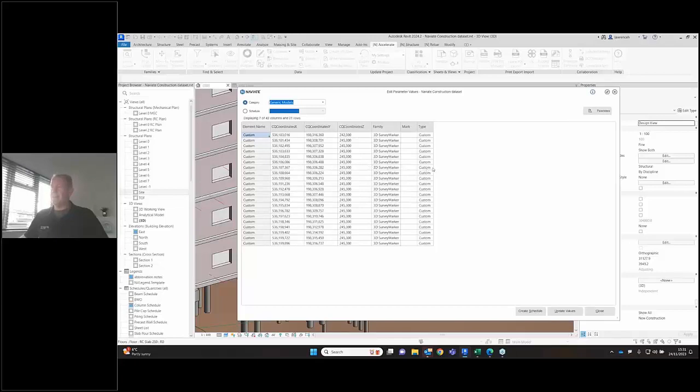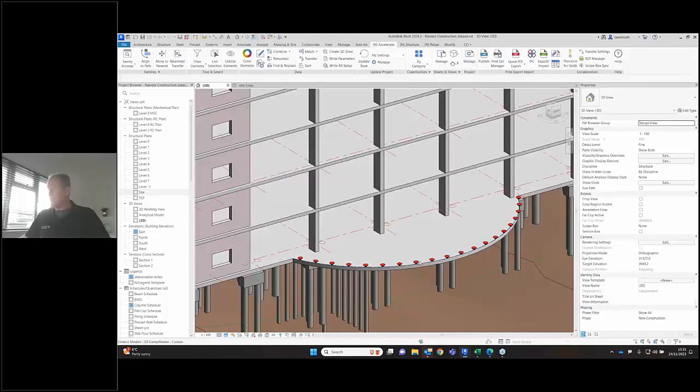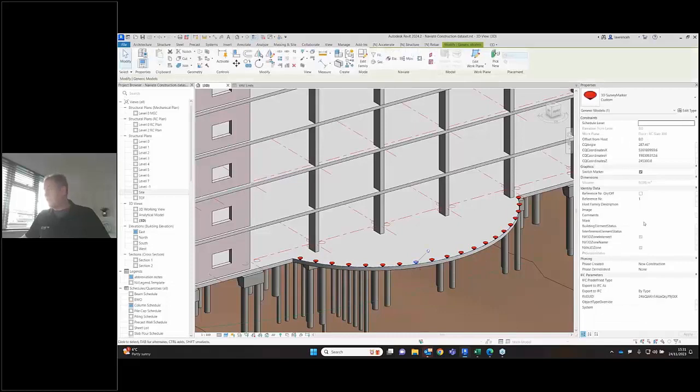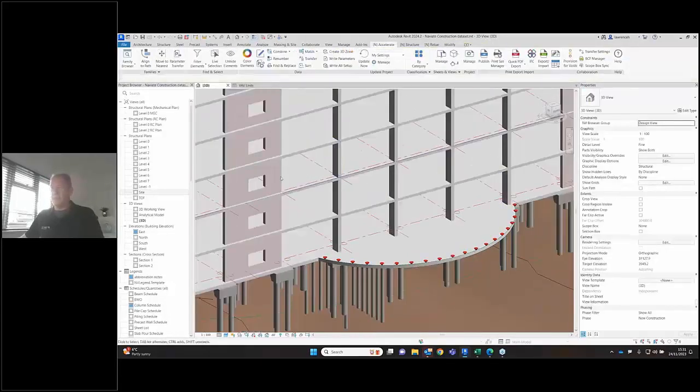However, this table again isn't particularly useful at the moment because we haven't got marks on any of the elements. So of course, if we're going to set this point out, what point is it? How do I know where that is? What we need to do is attribute a mark to each one of these elements. Now in Revit, that's a case of picking every single one of these elements, going to Mark, and then typing in some sort of terminology in there.